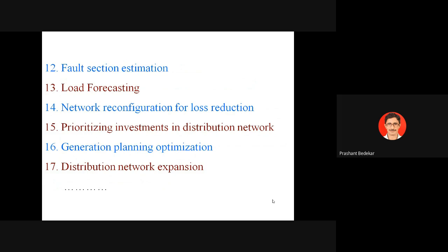In case of a temporary fault, the fault is cleared by opening and reclosing of circuit breakers. As we know, the circuit breaker opens and recloses 3 times, and finally, if the fault is permanent, it remains open. So in case of transient faults, the faults can be cleared just by opening and reclosing of the circuit breaker. We need not even locate the fault. Fault has come and gone. The relay sensed the fault, the circuit breaker opened, and before reclosing, the fault was cleared, so the circuit breaker closed and supply was restored.